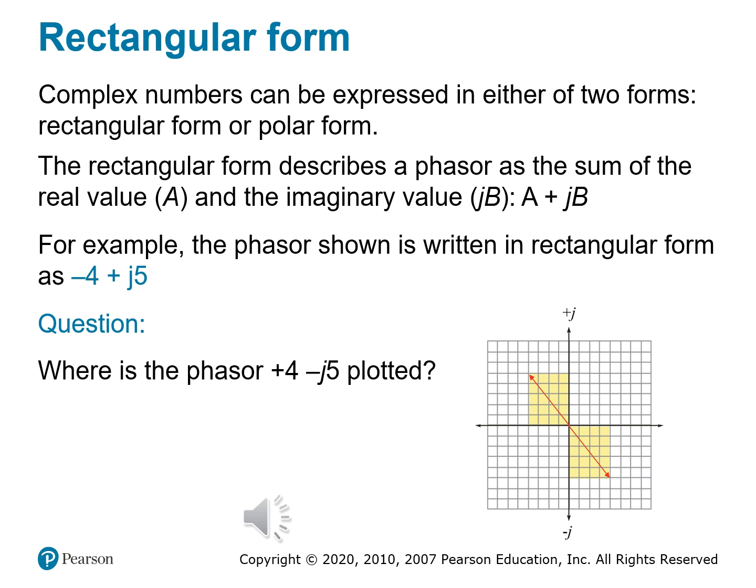And this is similar to how we broke down inductors into resistance and reactance, right? The real part was resistance, denoted by R, and the imaginary part was inductive reactance, and that was denoted by the JX. In this case, it was plus JX, right? Same structure, different component, right? But if we want to plot phasors, take a look at the plotted vector -4 plus J5. It starts at the origin and lands in the second quadrant.